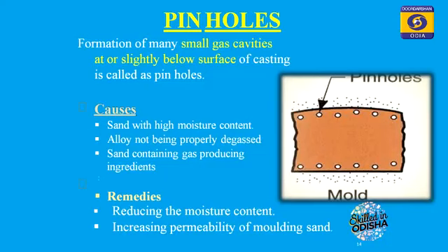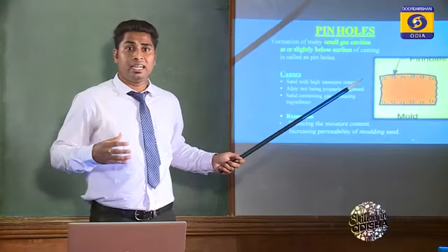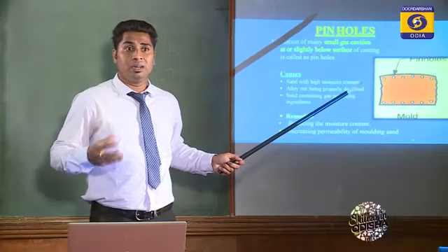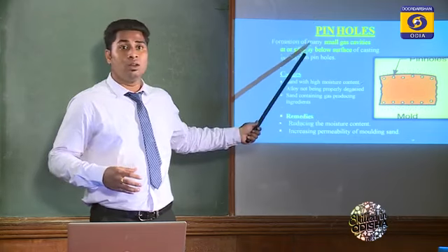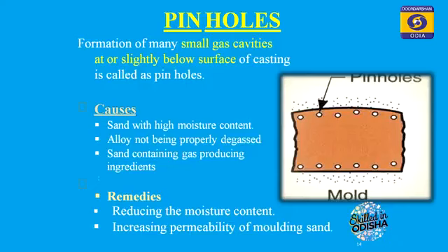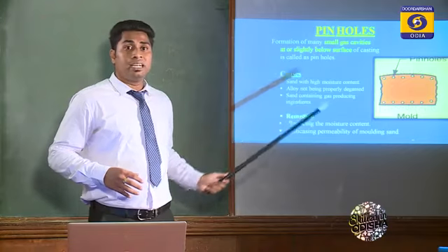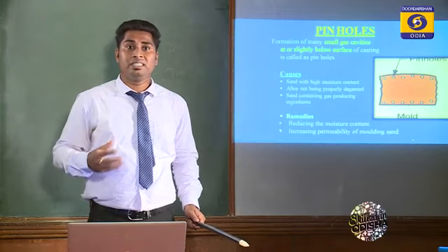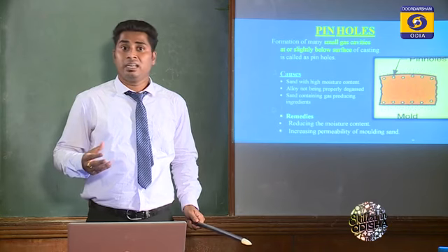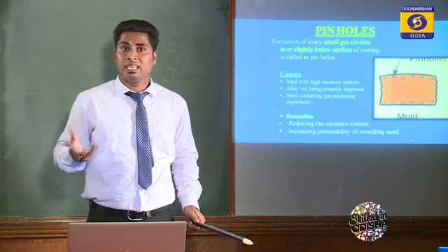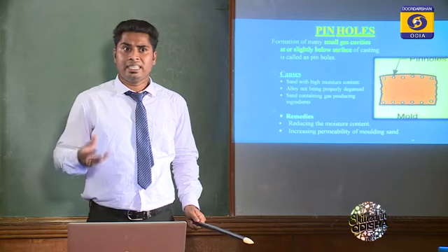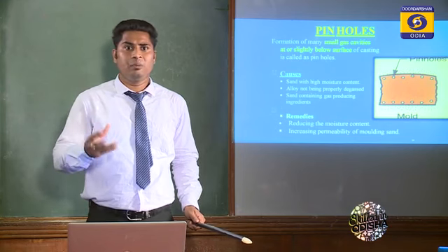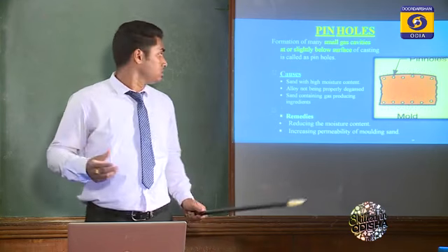If the alloy is not properly degassed, if gas is present inside the molten liquid metal, then pinholes will form. If the sand contains gas producing ingredients, and that kind of ingredients are present inside the molten metal, then they will definitely produce gas, and that gas will create the pinholes.